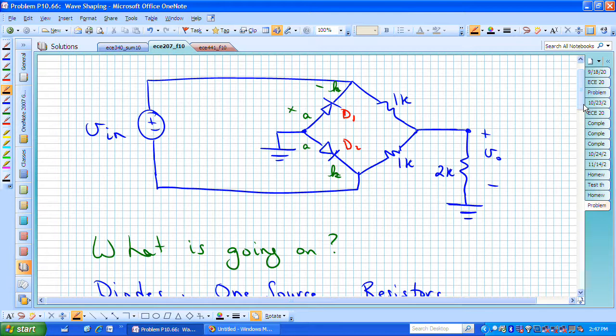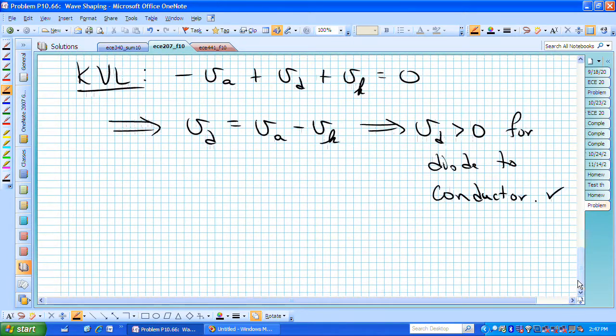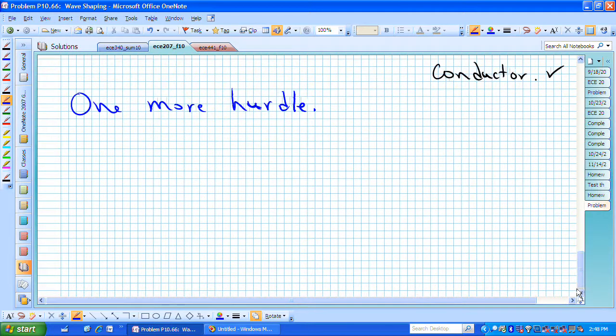The other thing that's a little bit tricky or maybe difficult to see in this particular problem is why these grounded positions. But if those are two grounded positions, the ground or the reference node is at the same potential, let's just connect those with a wire and get rid of that ground, and then we can figure out hopefully what's going on. That's the other hurdle that we need to deal with in this particular circuit before we can really feel comfortable with doing the analysis.